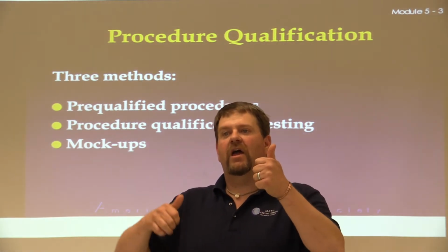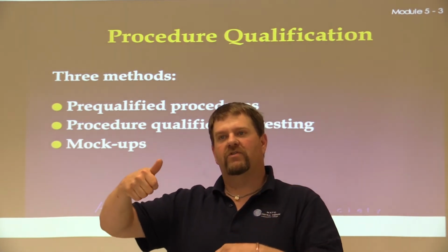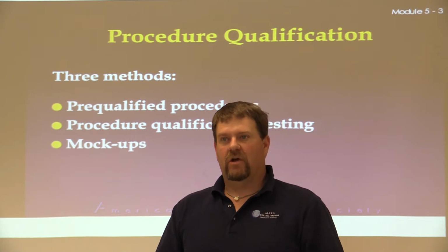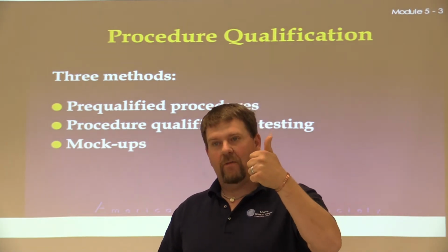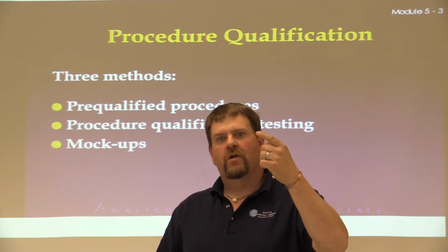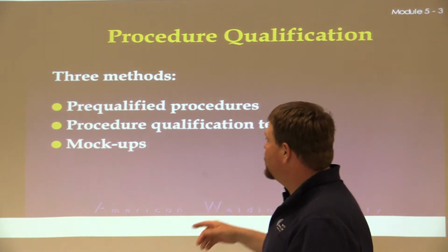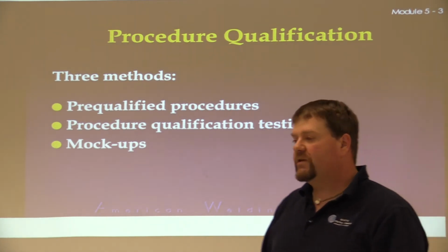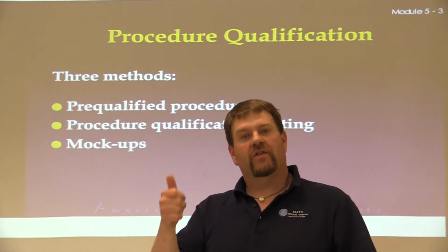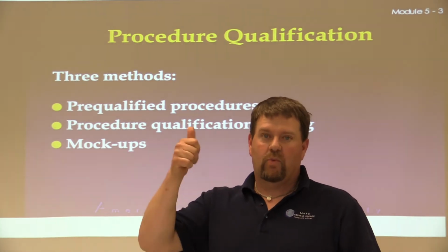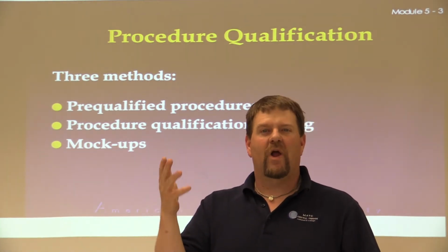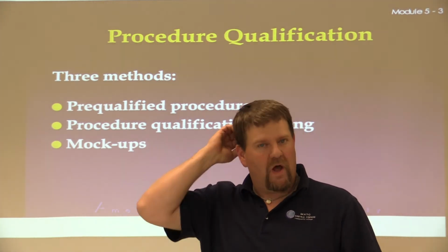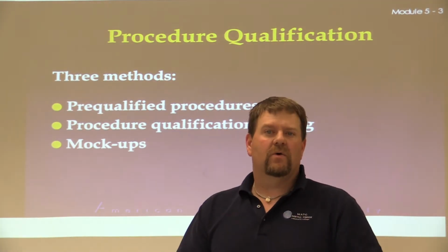Okay, so we've got guidelines, we've got the mechanical ability proven, so now we're going into the performance qualification. So we've got the WPS, the welding procedure specification, the PQR, the procedure qualification record, which we talk about here in a second. There's 3 different ones. And now we're going to go to the WPQR, which is the welder performance qualification record. And that basically is saying that they can weld that exact weld to the correct codes and limits.